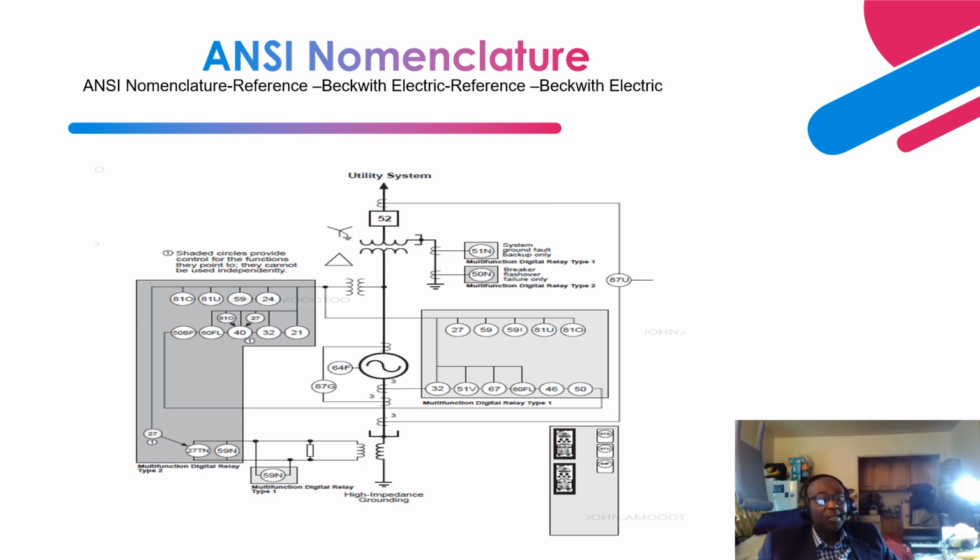Next is directional reverse power flow. Let's say you have a reversal of power flow into the generator from the AC grid, right? Then this generator is going to convert from a generator to a motor, and you don't want that. It's going to cause heating and failure of the generator. So that is when this relay detects that reversal of power flow from the AC grid.